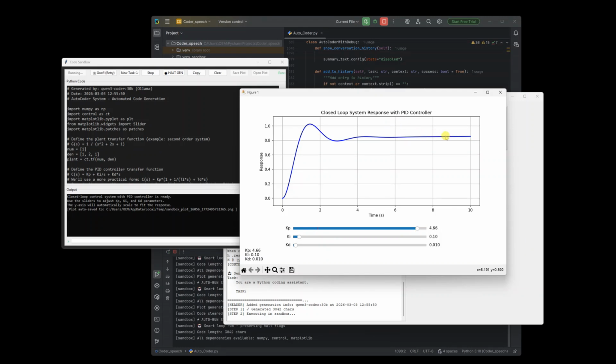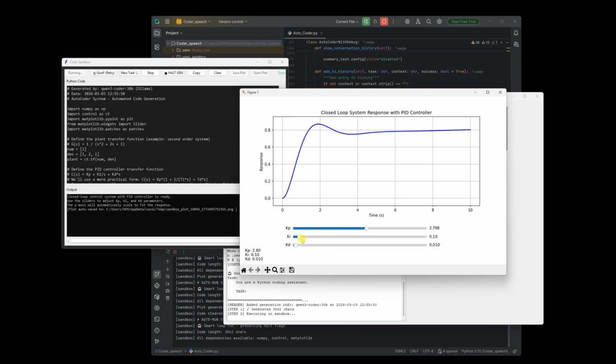So it's gone to about 0.8 something, not 0.9. So it's at the steady state error you can see here, as you'd expect just from proportional gain. So what we can do, I normally don't have the gain that high, turn it down a bit and introduce some integral action, and that should get rid of the offset.